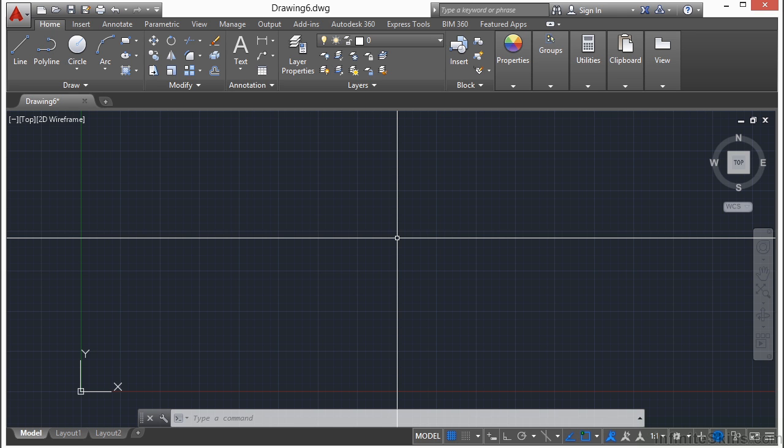Drawing units in AutoCAD are relative. It only interprets the units when you go to print your drawings, or compare it with other files that you've inserted or referenced. It will translate your drawing units to fit the way you tell it to on your paper. AutoCAD will take your line work and apply a scale factor when it prints. It will take the size of the paper you're printing on and scale your drawing objects accordingly.